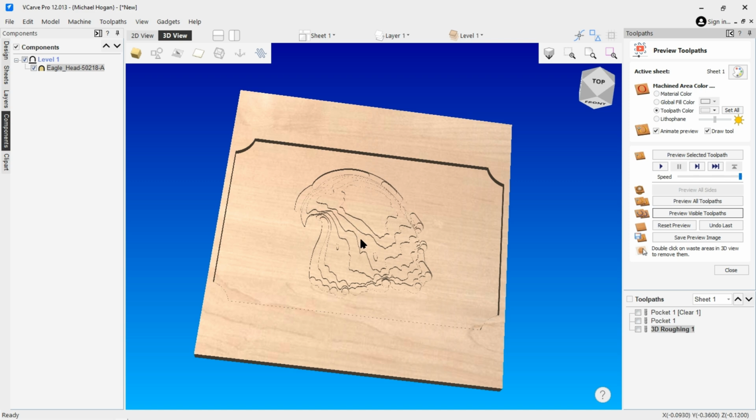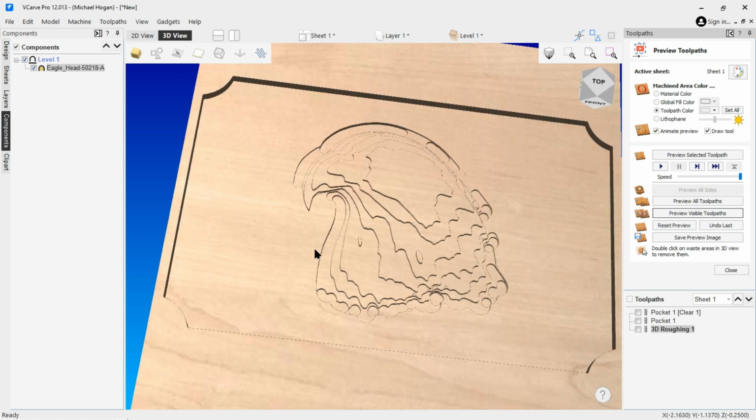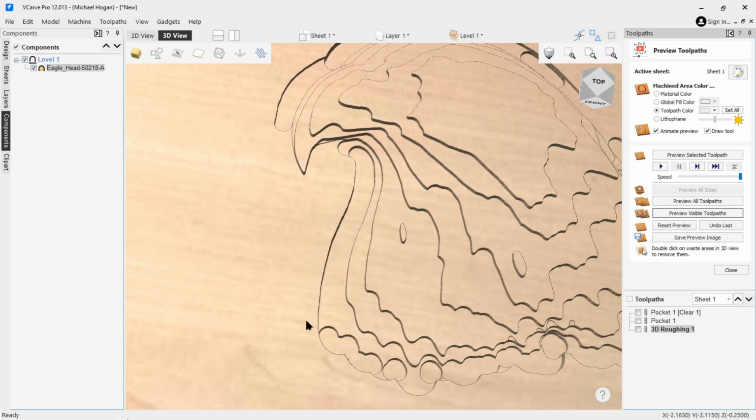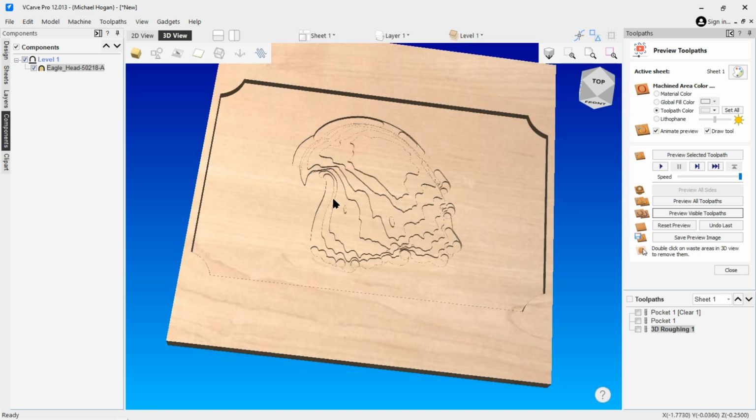That's to move the model upwards, or change the shape height of the model, or you can cut the pocket deeper. There's three different ways you can make the adjustments there. So here you see the outside, it's cut. In fact, we'll do the finished tool path, and then you'll be able to see it a lot clearer